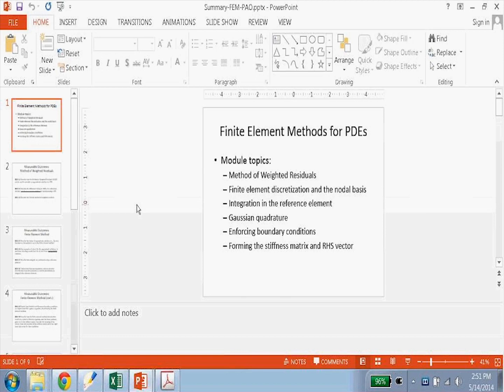And then just remember the finite element notation that we talk about element I as being the piece of the x-axis that lies between xi and xi plus 1. The element to the left is I minus 1. The element to the right is element I plus 1. And what's key about these basis functions is that they're 0 in most of the domain. The only place where Phi is non-zero is on element I minus 1 and element I. And we use that fact when we get all those integrals that come out of the definition of the weighted residual, that a whole bunch of the integrals go to 0, right? Because you're multiplying things together that are 0 on big parts of the domain.